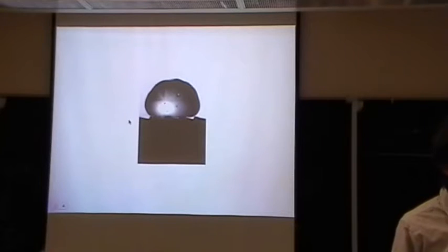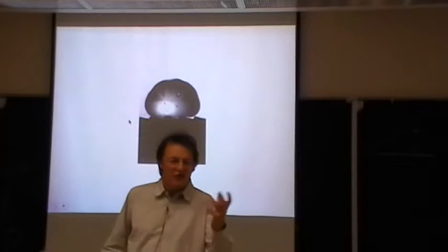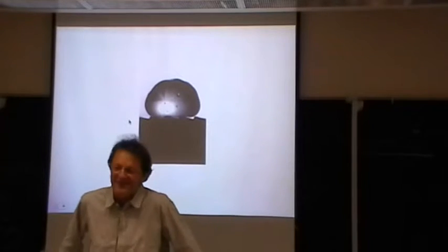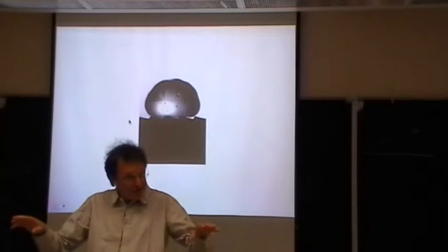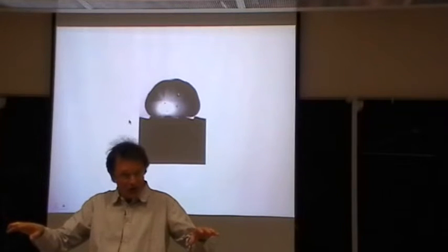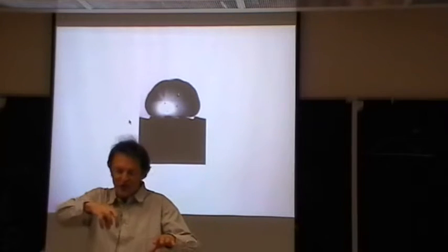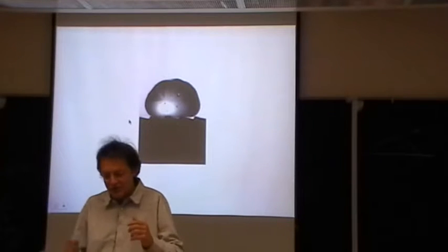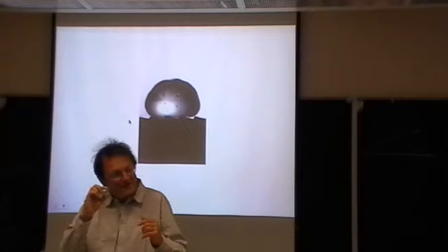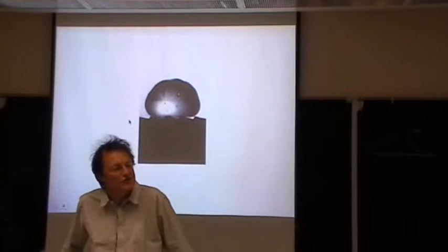Couldn't you do something similar with a thermal gradient? You asked a very painful question too, because we thought about that, and we spent a few months with a student of mine trying to place levitating drops on surfaces where you have a gradient of temperature, but it levitates everywhere. Let's say 300 degrees here, 400 degrees here, and you place a drop. And we never observed anything, despite the fact that, for example, the temperature impacts the thickness of the film. If the thickness is not the same, you make some kind of asymmetry, and so you might generate some motion. But we never succeeded in doing that.